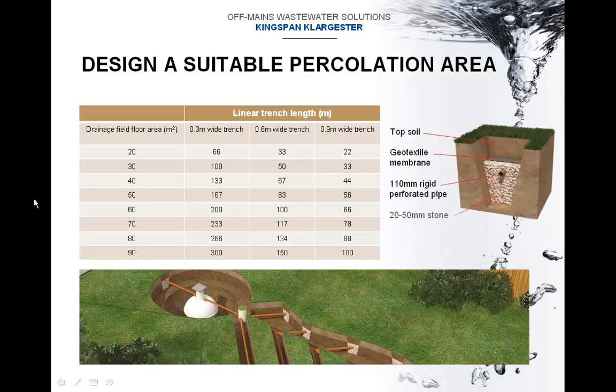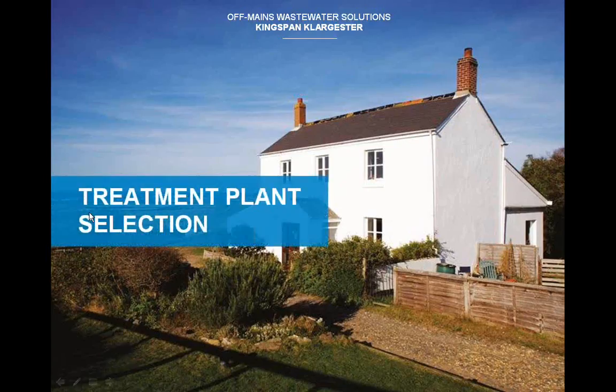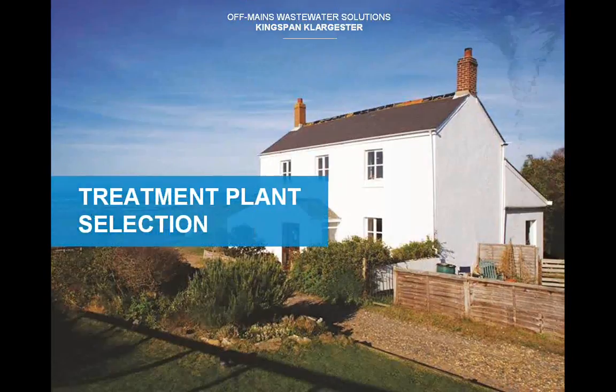Once we have our figure A, we can then divide by the trench width, which is typically 0.6 of a metre, to give ourselves a linear meterage of soak away requirements. Next we move on to treatment plant selection.